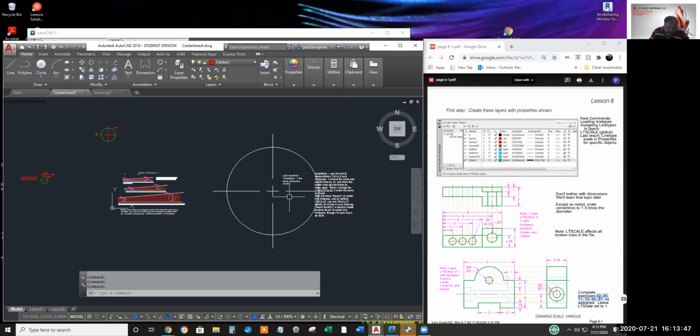How to put this? When we create, we'll learn dimension styles. I think week number 8, and for radius and diameter dimensions, you can have it put a plus sign in the middle of your circles or nothing in the middle of your circles, or you can rig it so it puts the entire bullseye set. But again, you're kind of stuck with a carved in stone whisker length.